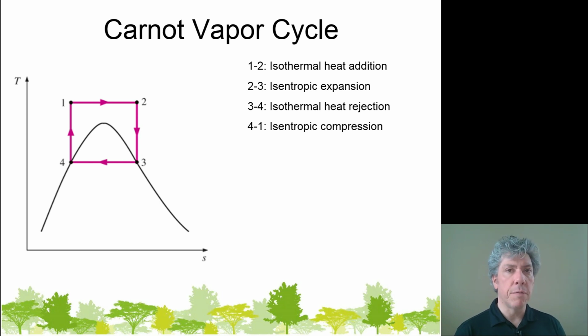If the working fluid goes back and forth between the liquid and the vapor phases, then the cycle diagram will have to be superimposed around the vapor dome somehow. So if we consider the TS diagram for a Carnot cycle, it's just a rectangle, and we can superimpose that rectangle on top of a vapor dome. If we put it where one of the processes is above the vapor dome and the other one, from 3 to 4, for example, is below, and the other two are just vertical, then it kind of makes some sense if you think about it.